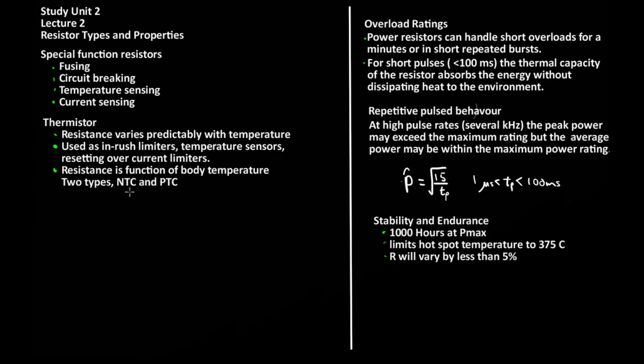Thermistors come in two different types, NTC and PTC. NTC thermistors have a negative temperature coefficient, and PTCs have a positive temperature coefficient. In a negative temperature coefficient device, the resistance will decrease with temperature. In a PTC device, the resistance will increase with temperature.